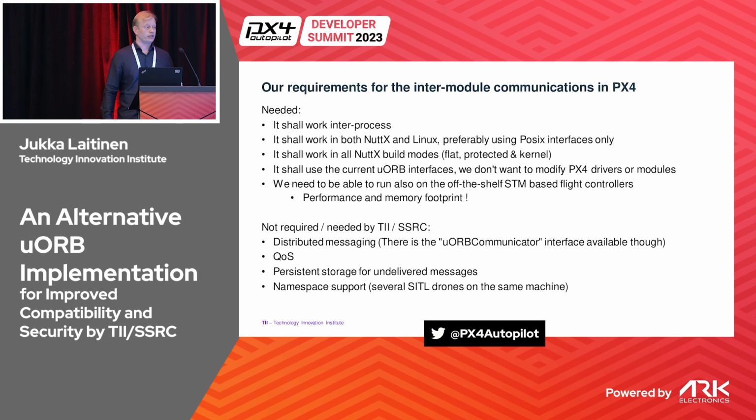It should also work in all NuttX build modes, because we're using all of those in our different software configurations. And it has to use the current uORB interfaces, because we don't want to modify every PX4 module just to get our own messaging in place. That would be insane. We want to use PX4 as is, because it's great as it is.